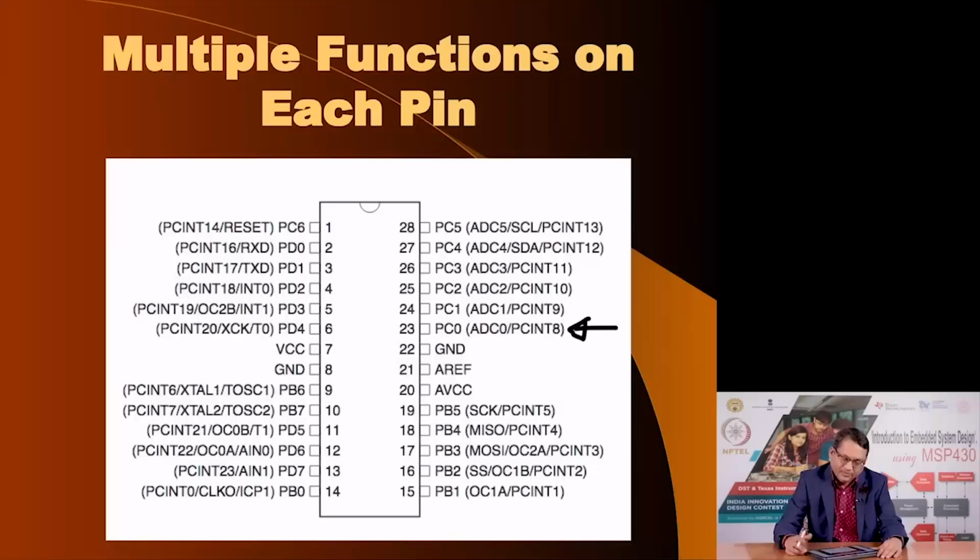Here we can go back and look at the pins of this AVR microcontroller, and you notice that it has a VCC and an AVCC. This VCC is for the logic part of the circuit inside the microcontroller, and AVCC is for the analog VCC, specifically the ADC and the voltage reference source. And it also has two grounds, although it does not explicitly mention it. This ground is paired with this digital VCC here, and this ground is paired with the analog VCC.